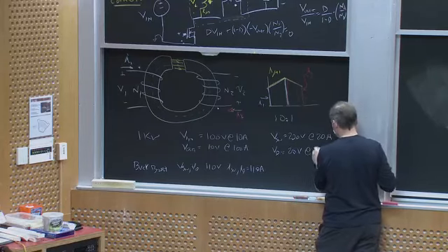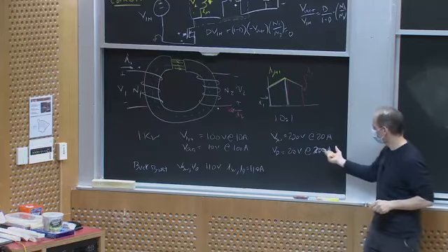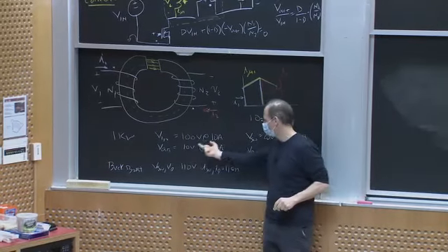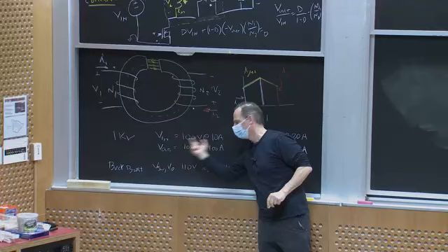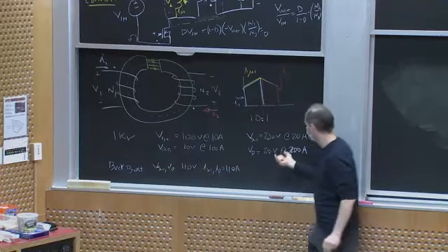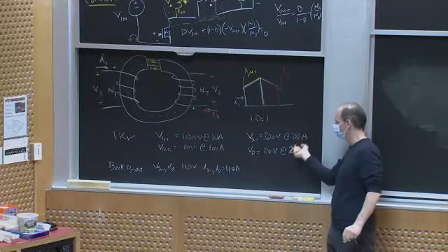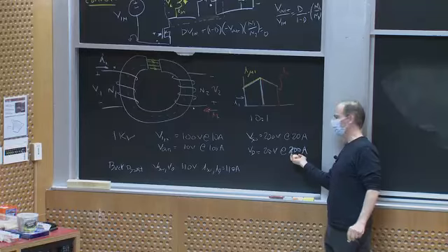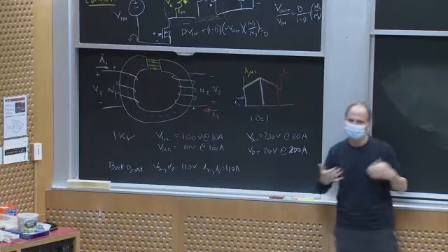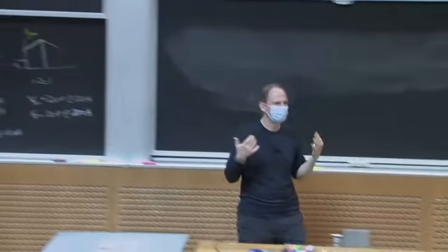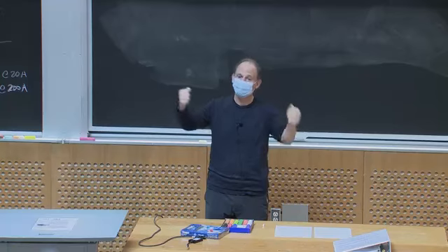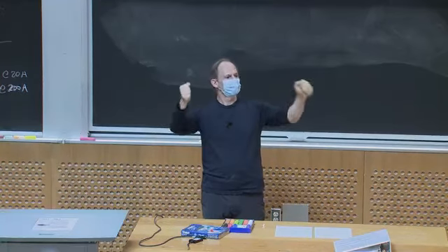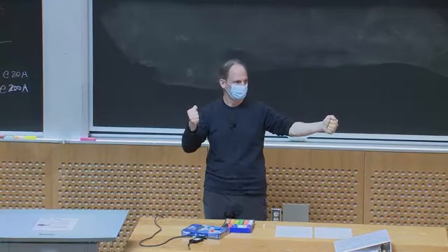Okay, so what it's let me do is, instead of needing a switch that has both high voltage and high current, I get a high voltage low current switch and a low voltage high current diode, right? And I might be more easily able to buy those components, or at any rate, I can choose my turns ratio to rescale voltages and currents to be more favorable.